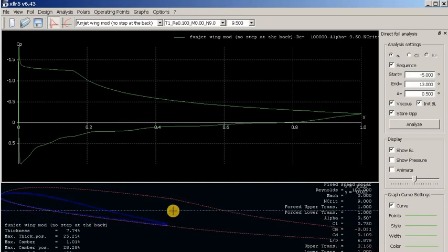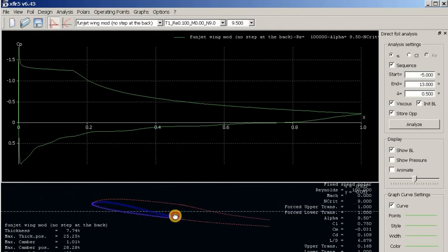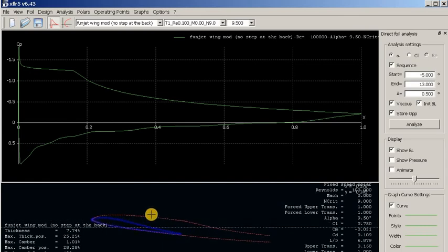And then if we zoom out, this software is basically XFOIL simply written in C. So the simulation area is finite, and it does not converge back to the laminar flow. So we have the turbulence in the back. That actually happens exactly like that in reality. So once again, we have the separation happening, and we see that these things continue to be turbulent. And above the boundary layer we have the laminar flow.